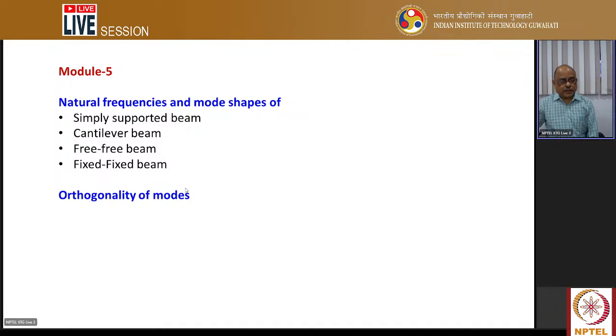Decouple here means that the equations of motion are converted into a time domain equation in discretized generalized coordinates. In this sense it is decoupled and becomes an individual equation of motion, just like the motion of a single degree of freedom undamped or damped system.